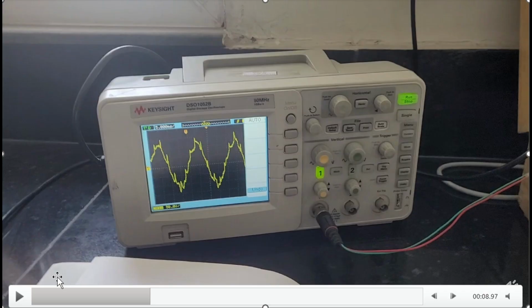For example, it could be insufficient delay between the output samples. While generating a sine wave, a sequence of digital values stored in a lookup table are sent. If the program runs very quickly, then the DAC output changes very quickly. The oscilloscope may not display a perfectly smooth waveform and may show such small distortions. It could also be because of electrical noise or poor grounding, because these disturbances can appear as fluctuations on the sine wave.